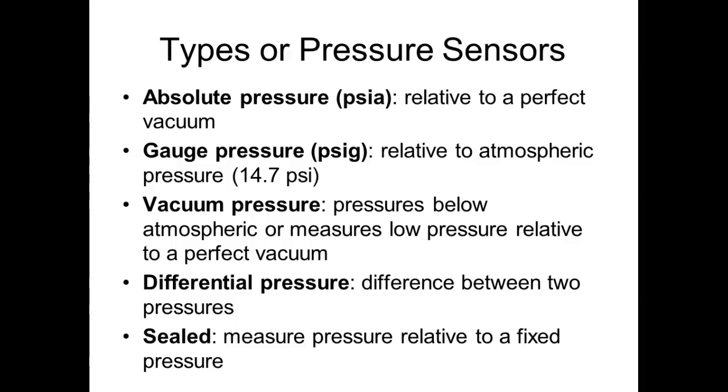What your gauge is measuring is the differential pressure between the high pressure and the low pressure, and that shows you how much Freon you're supposed to put into your system at a certain temperature, by the way, guys, because gas pressure varies with what? Temperature. So if you ever worked on an HVAC system and did it right, you look at those gauges, then do a formula that compensates for the temperature, and that's how much Freon you put into your system.